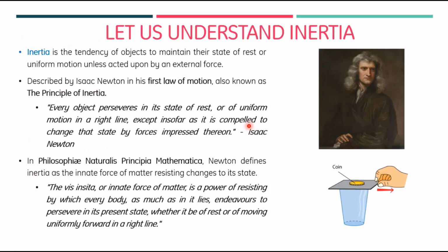So now let us understand our main topic, that is inertia. We talked about how, when there is a small load generation variation, power system inertia is there to damp the impact of such load generation variation on the frequency. So what is inertia? In terms of physics, it is the tendency of an object to maintain a state of rest or uniform motion unless you put some external force on it to change its speed, velocity or angular velocity. Until you do that, it will try to maintain whatever state it is in.